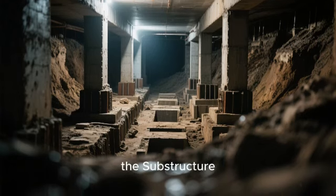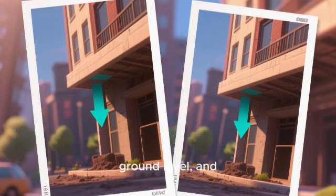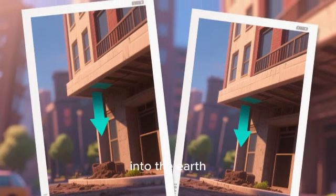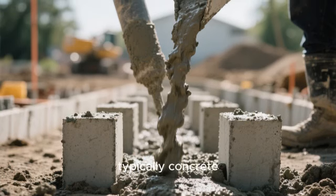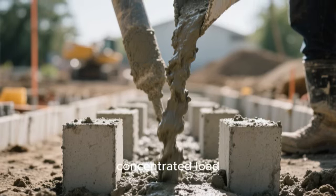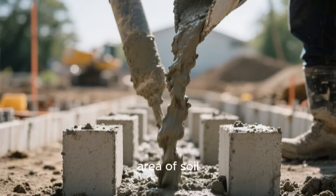Let's start at the very bottom, with the part of the building you never see but is absolutely critical, the substructure. This is the part of the building below ground level, and its primary job is to transfer all the loads from the building safely into the earth. The main components here are the foundation and the footings. The footings are the widened, typically concrete elements at the base of foundations that spread the concentrated load from columns and walls over a larger area of soil.